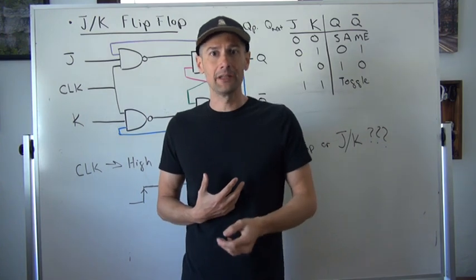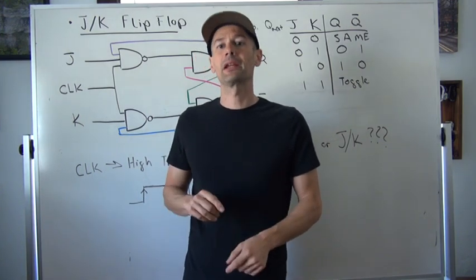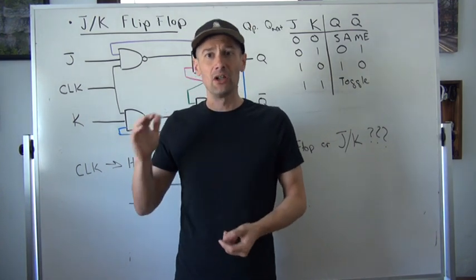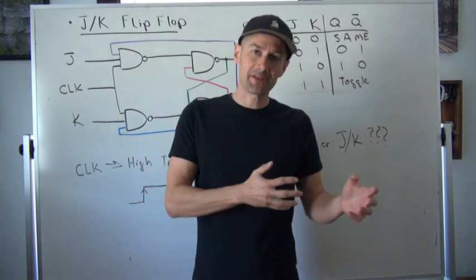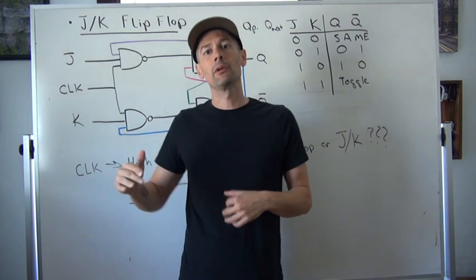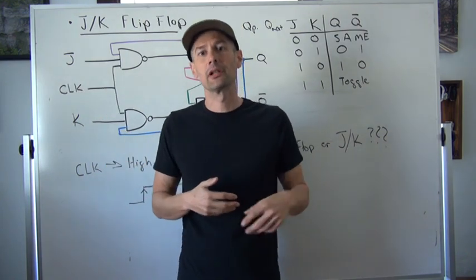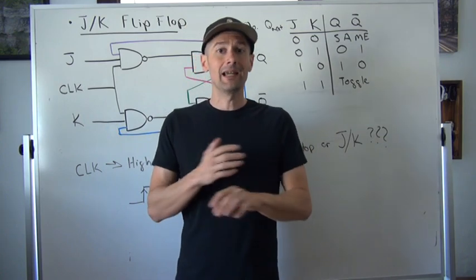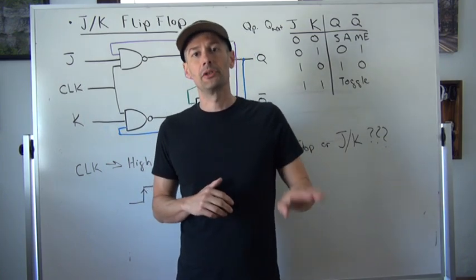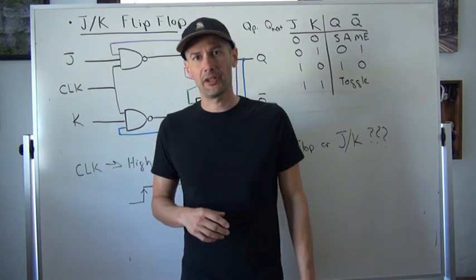The D latch only had an enable signal and a data signal: as long as D was high, we were in a set state, and if D went low, we were in a reset state where Q would go to 0 and Q bar would obviously be reversed. And we avoided ever having Q and Q bar be the same.